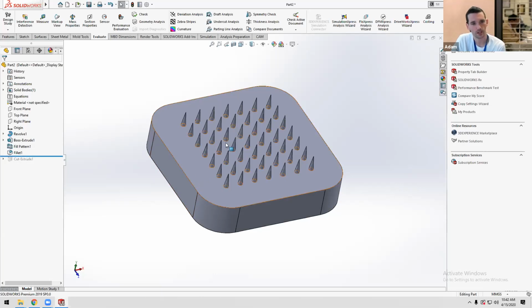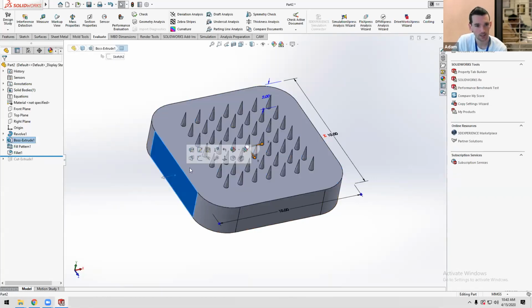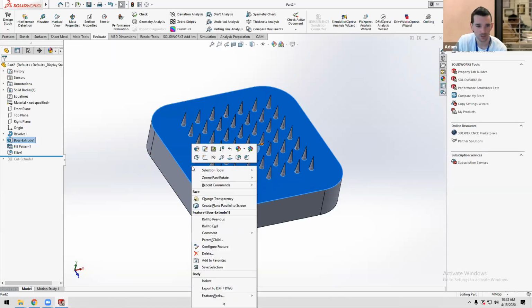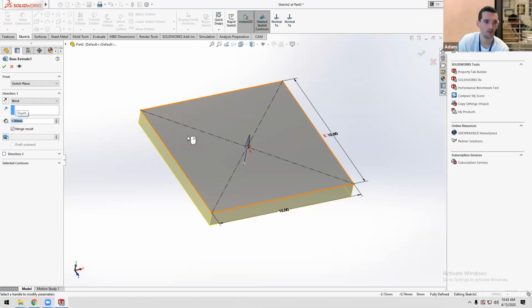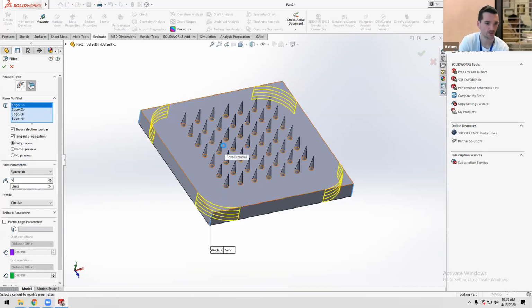Not that specifically, but if I want to go make edits and I don't remember which one it was, if I click it, it'll be highlighted over here, right? And then I can also right click directly on that feature to go edit. So feel free to right click on the feature that you want to edit, and that's a faster way to do it.